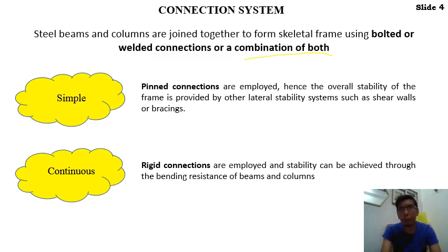The good thing about rigid connection, as I mentioned, is that you don't need support components like bracings or shear walls, because the sizes of the beams are already big and strong enough to support the moments and the load. So they can transfer the load simultaneously without problems, from beam to column straight down to our base footings.